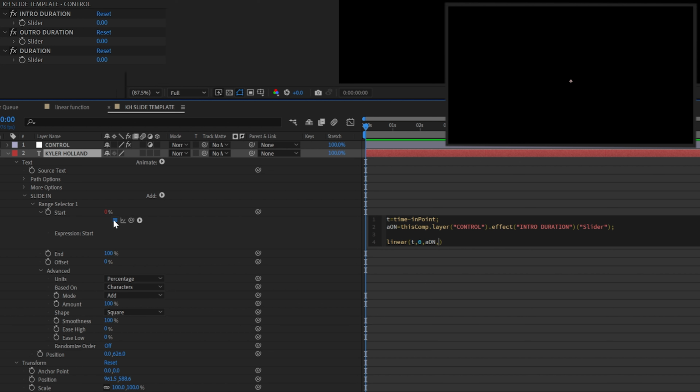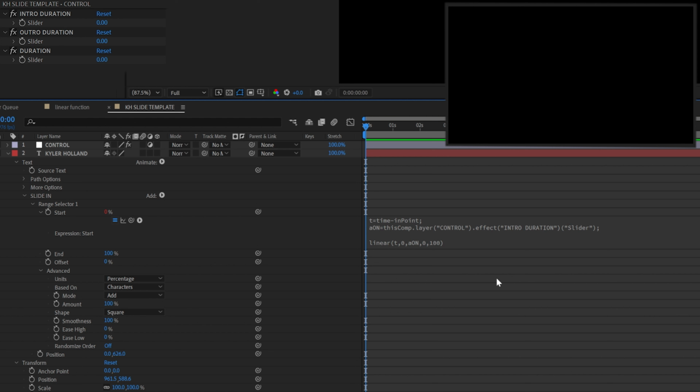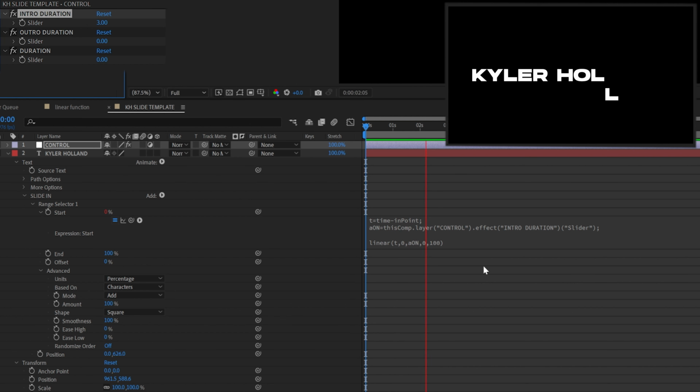Well, I just showed you earlier that from 0% to 100%, our start animation happened. So simply type 0 to 100. And then once you're done with that, you can click away, and you'll see that if we play this, nothing happens. Well, that's because we've never actually set the intro duration up here. So let's set this to 3 seconds. And as you see, when we play this along, in 3 seconds, our slide animation is going to happen.